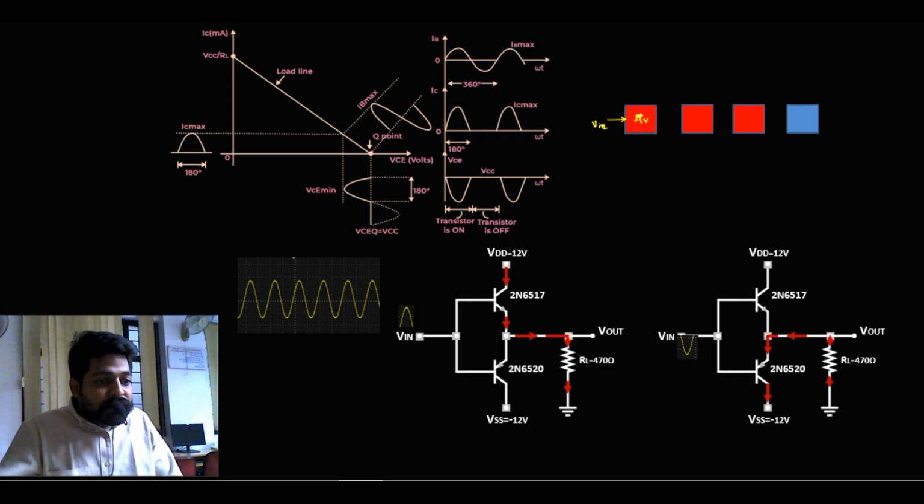It has a gain of AV. Suppose that AV is not enough, I will keep another voltage amplifier with the gain of AV2. Like that I will keep multiple amplifiers, up to which I get the strength I need. But in the last stage, I need another kind of module, which has to deliver the maximum power for the loudspeaker.